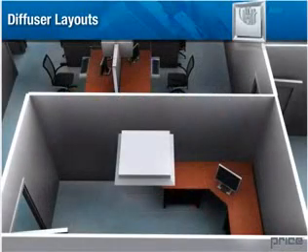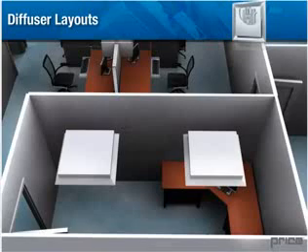3. Undersupplying. When dealing with larger rooms, try to use more than one diffuser to supply air to the space. Believing that money will be saved by putting all the air through one diffuser will cause more problems in the future.